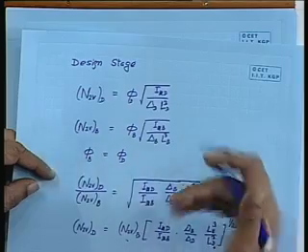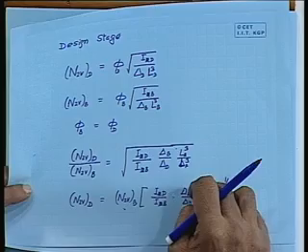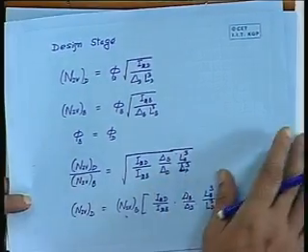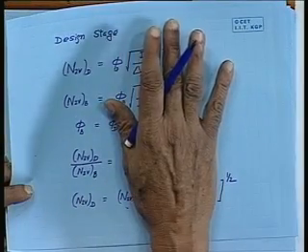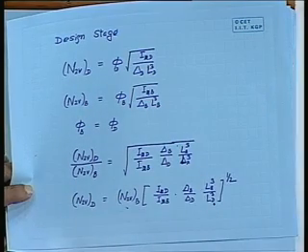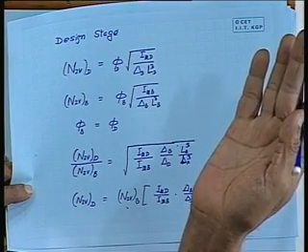Okay. So, one thing is still a very big question mark: how do you select the basis ship? You have to select the basis ship on the basis that it meets your requirement of the proposed design. What was the design requirement at that time, and what are the design requirements today? If the requirements are identical or very close to each other, I think you have chosen a good basic ship, and the difference between the size should not be much higher.